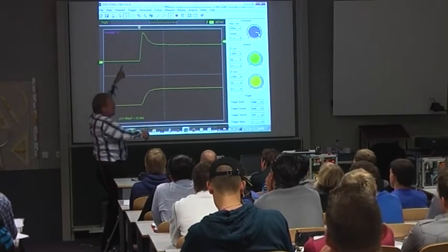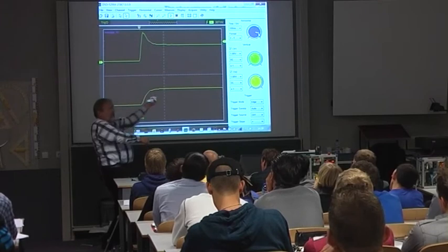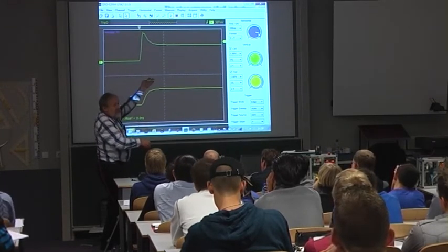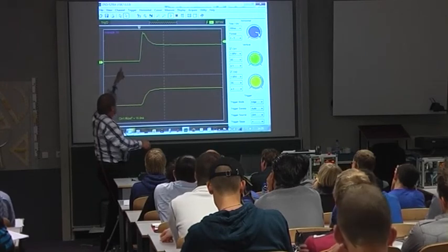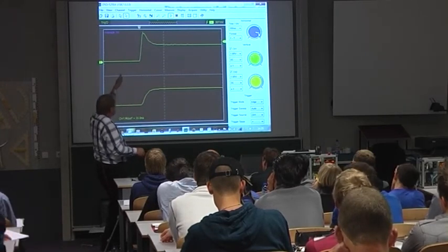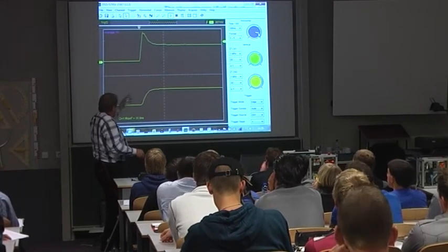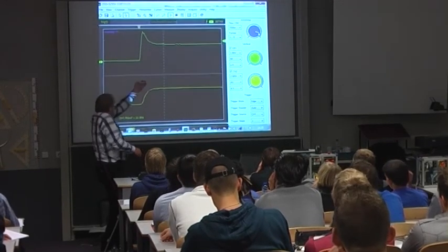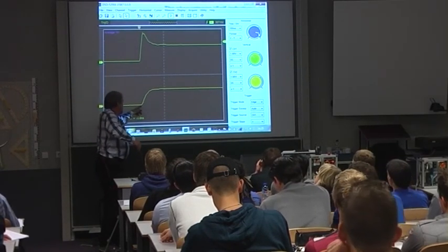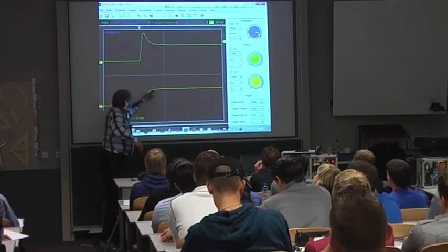So initially you get 3 volts. And then it goes down in an exponential curve to the steady state value, 1.5 volts. Well, my scope is not fast enough to really see the 3 volts, but you can see at least the difference. It's trying to get the 3 volts and then going down. And here, initially there's no current, so 0 voltage. And then it takes some time for the curve to go.